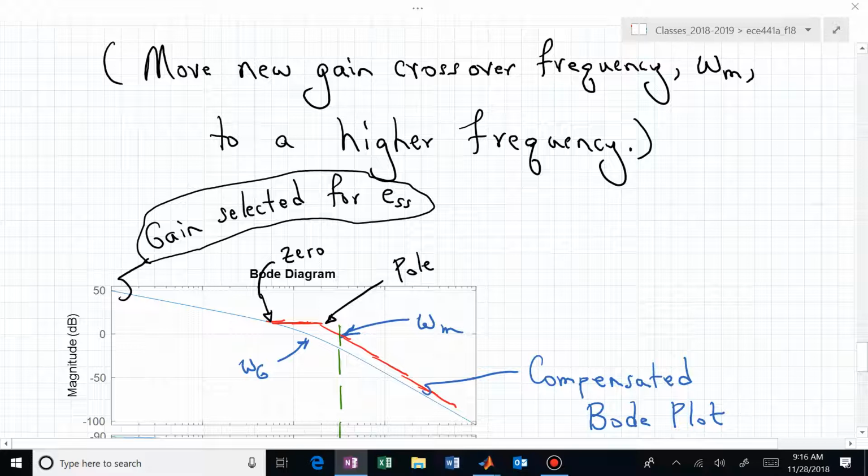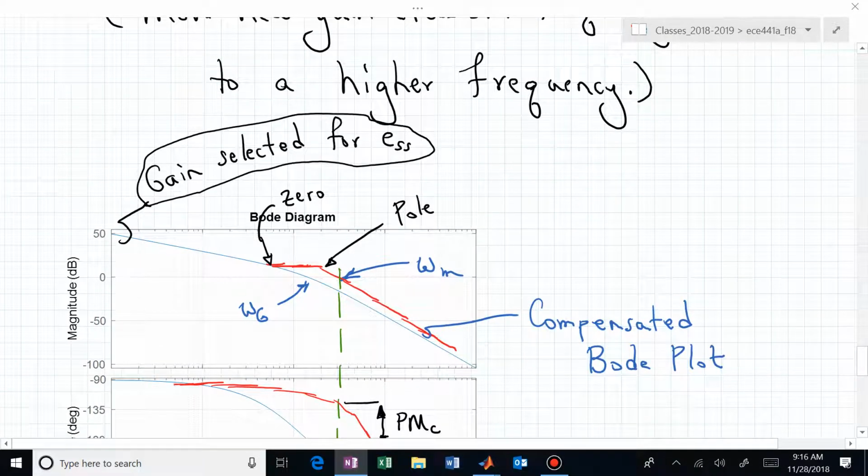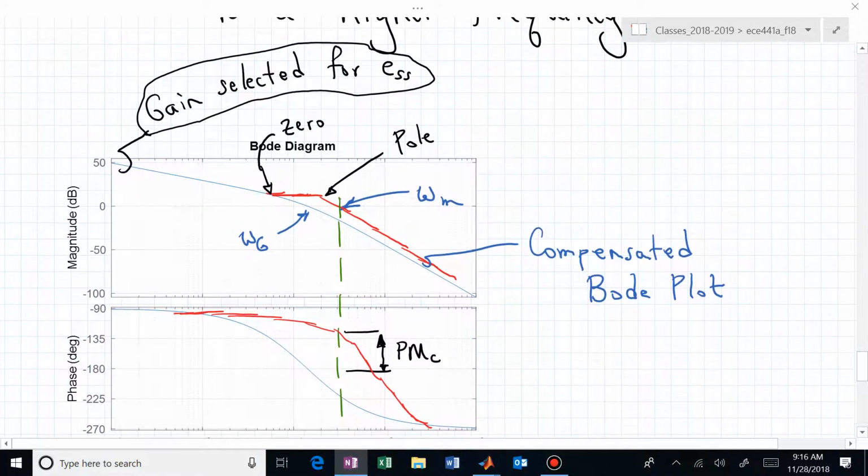But here, one way to maybe keep the designs straight in your own head is to say, well, let me just use omega sub m for phase lead. What are we doing now? Well, now we actually look at the phase margin based on the blue curves. And in this particular case, we have a phase margin of 0. We want to now maybe achieve a much bigger phase margin. In this case, I'm achieving a phase margin of about 45 degrees or more.